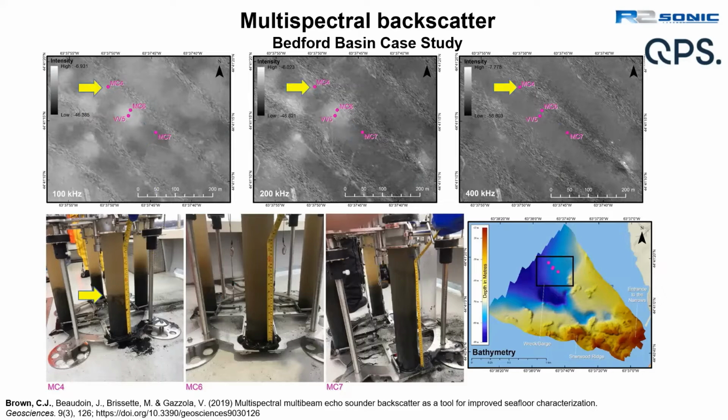We got a little bit off onto an area that's starting to get a little bit higher backscatter on the lower frequency. We get a little bit more penetration. And right on top of those hard spots, we only get maybe a couple of centimeters, and physical grab samples also brings up some of that coarse gravelly material underneath. So we're pretty confident what's going on there. There's a frequency response. We're crunching through that mud layer with the low frequency.